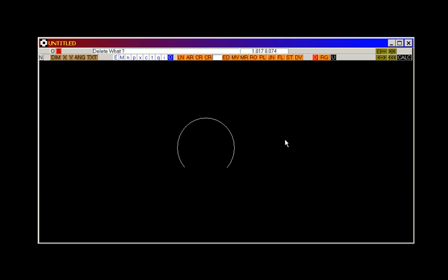I'm going to delete this line. That line is still complete. I'm going to go up here and undo that delete. I also believe that there's an element here that I don't want. Yes, okay. I want just a single arc there. Make the drawing with as few elements as possible. It's important for matching. If this tool was going to be matched from information coming in from DXFs, you'd want it to be drawn with a single arc, which is how it's going to come in.